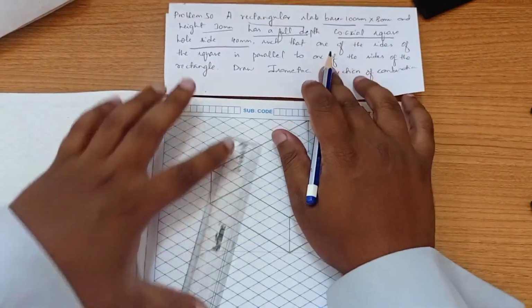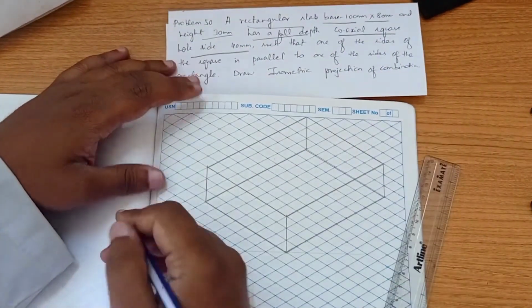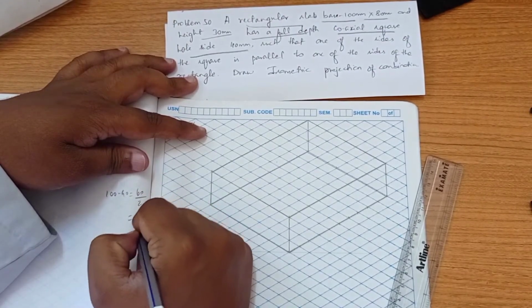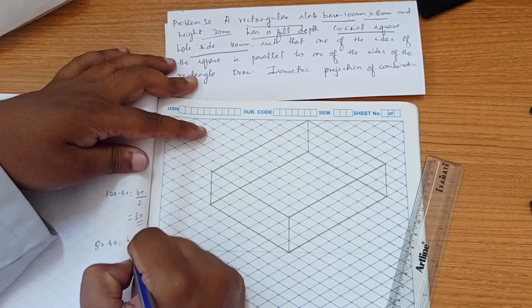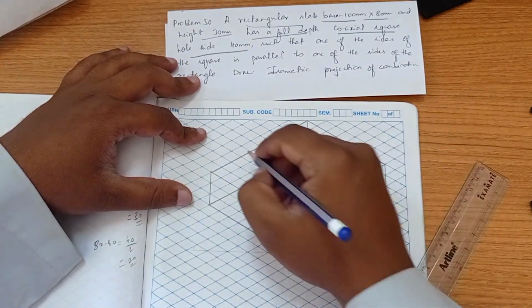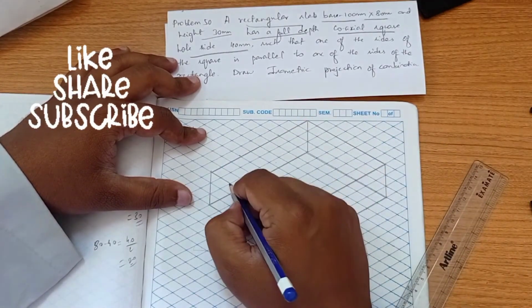30 means 3 boxes. Now we have to make a square hole of side 40. So 100 minus 40 is 60, divided by 2 means 30. Then 80 minus 40 is 40, divided by 2 means 20. So on the 100 mm side we have to mark 30, and on the 80 mm side we have to mark 20.